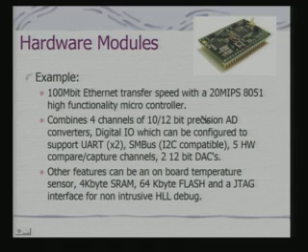Now, these kinds of products are available today. Why are they available? You can add such a card to your appliance and very easily provide Ethernet connectivity. It has I2C compatibility, so using the I2C, you can connect it to your main system and have data transferred to this kind of small footprint device, so that you can plug your appliance through this card into an Ethernet port and have Ethernet enabled connectivity.